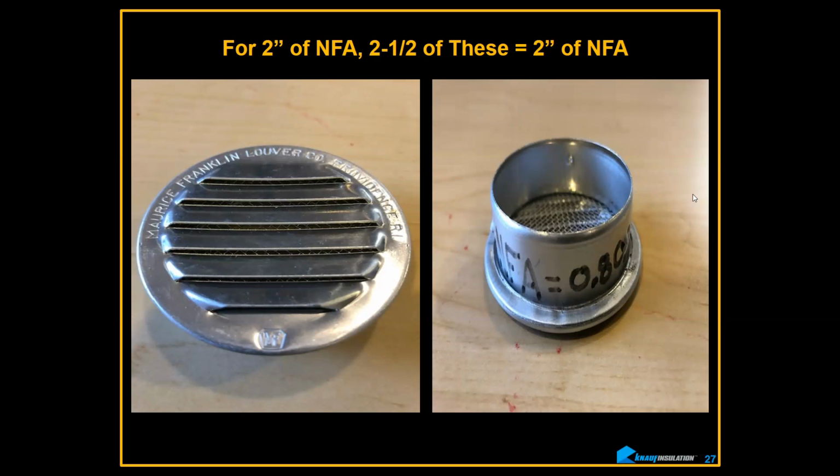Oh, I did want to mention, I'm not a big fan of inset stapling for kraft facing either, and I learned at the RESNET conference, where I conned Rick into doing this webinar for us, that the new RESNET protocol is going to, by default, give kraft-faced inset stapled batts at best a grade 2 installation.